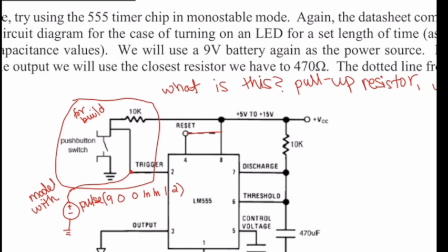It's a combination of the RC, so the R5 and the capacitor. The combination of those two is what is creating that. So when you hold one fixed, then you change the other. It's increasing or decreasing the time it takes to charge and discharge. Yeah, it's creating that.